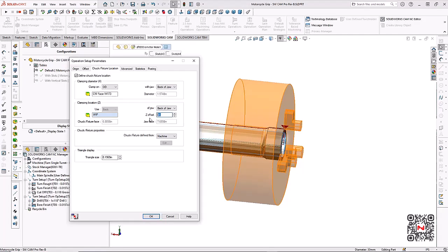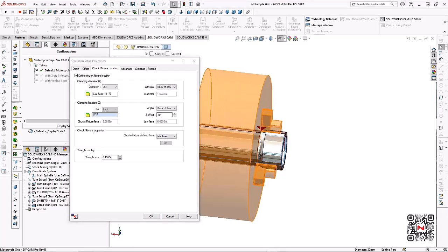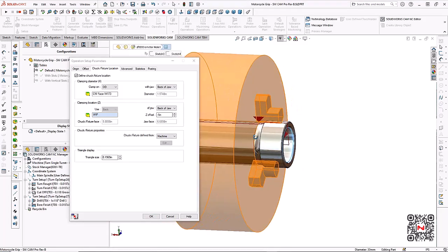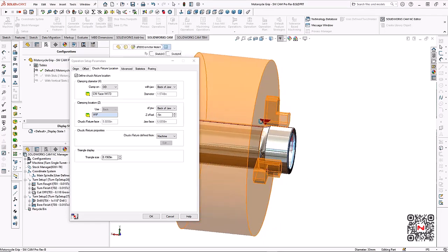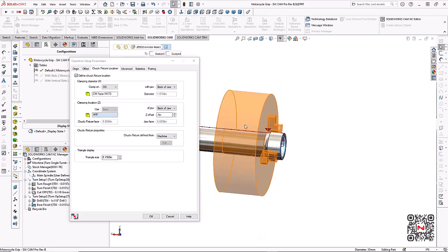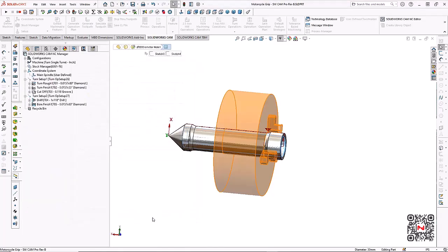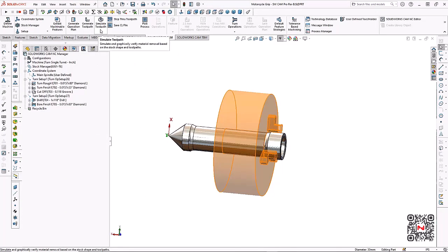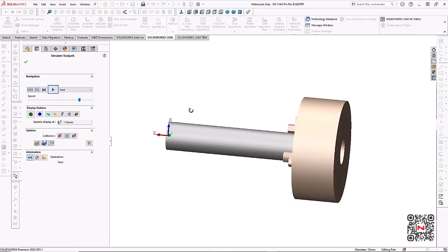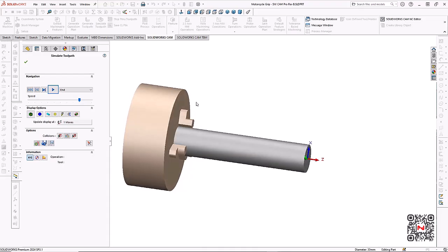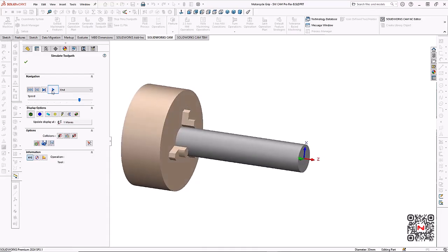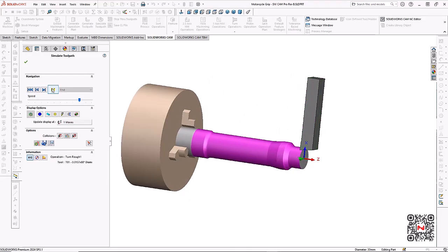And then I can offset it and go back just 1 inch, for example. And that would be a nice place to grip that part for the second operation. So I'm up close to the front of the part there, and I have good stability there. Say OK. And now we can go ahead and run simulation again. And remember, on the first operation, this would be here. The main spindle might be here on the left, and I can go ahead and simulate the turning again.